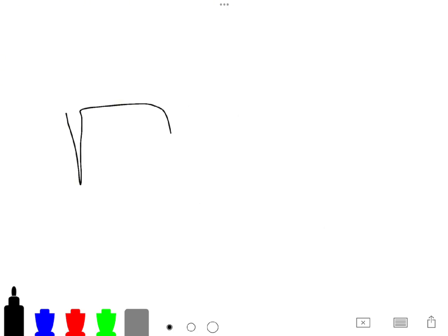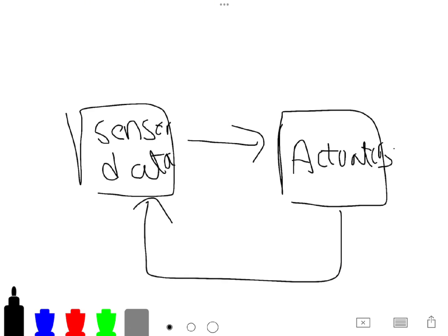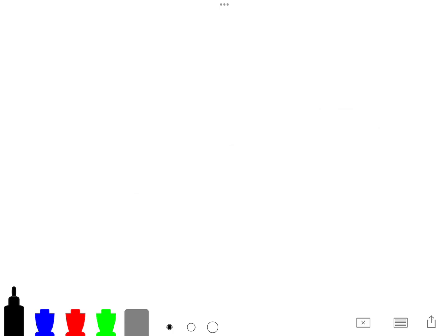At the core, a control system takes sensor data, for example, orientation or velocity, and calculates how you can adjust the rocket's actuators in order to counteract this change and ensure that the rocket maintains a stable path of flight. This is essentially what's called a control loop: measuring something, actuating, getting feedback, and then doing it again, and again. These loops run dozens or hundreds of times per second in order to maintain this path of flight. Now, there are two ways of doing this.